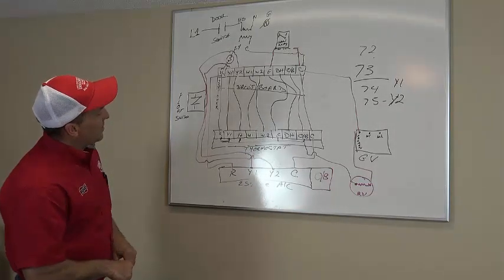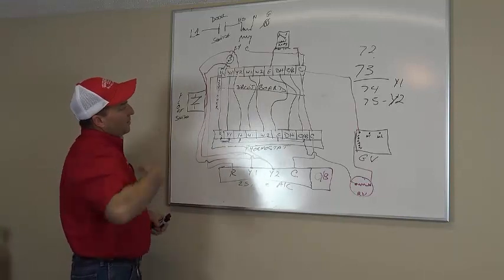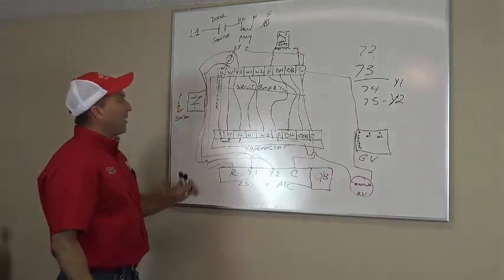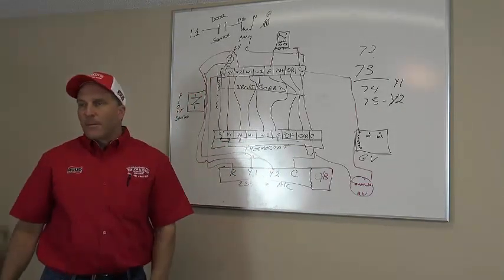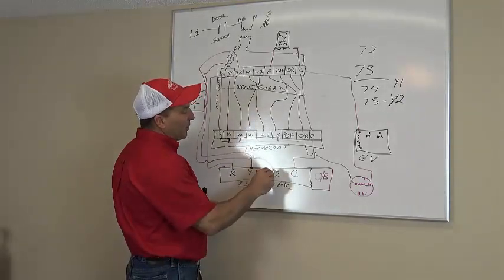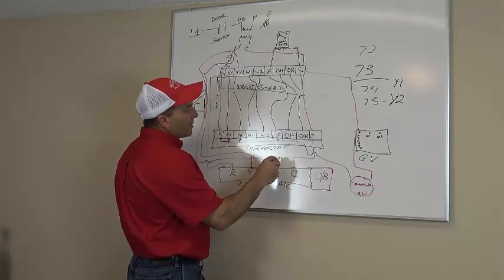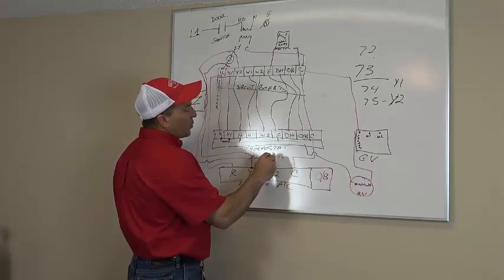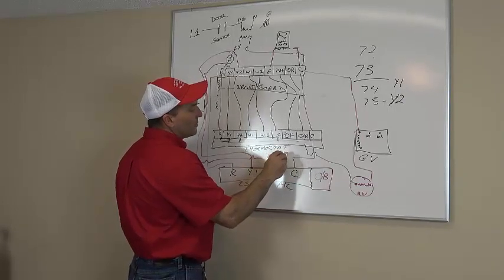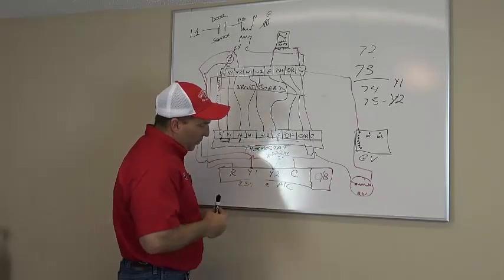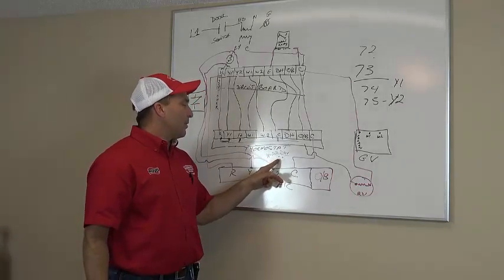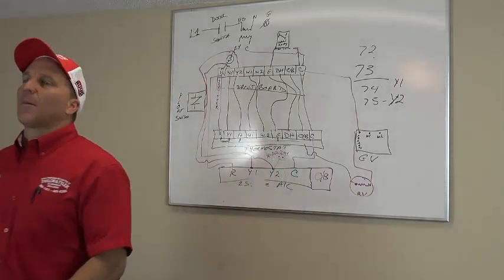Now, what happens, guys, if I am running this system and I am not in heat pump mode? I'm running my air conditioning system in Y2. And what happens if Y2 is going to energize? It is going to energize a solenoid valve, which is going to bring 18 to 22 DC voltage, and it energizes that solenoid valve in my compressor. What happens if it does not send voltage to that solenoid valve in my compressor? Tell me what happens then.